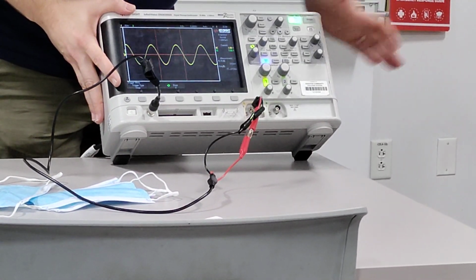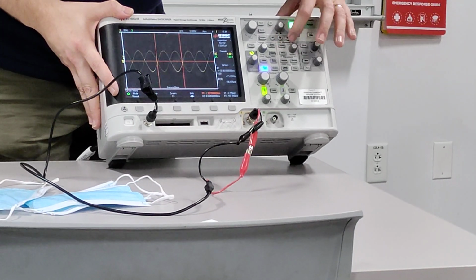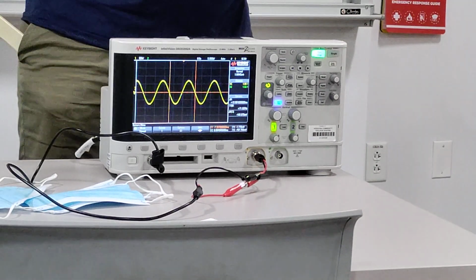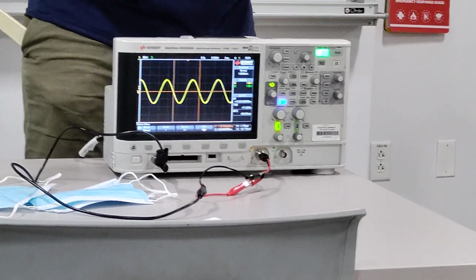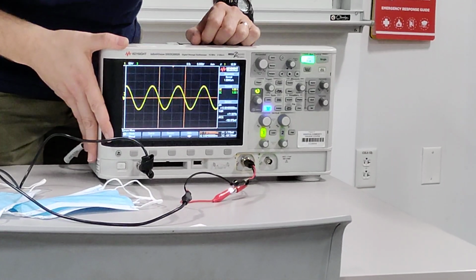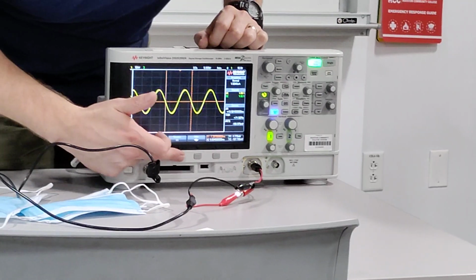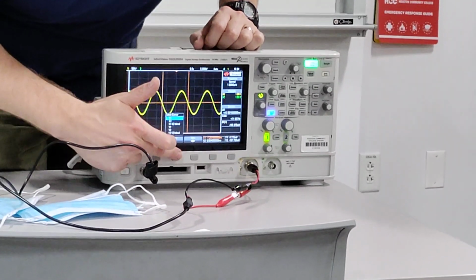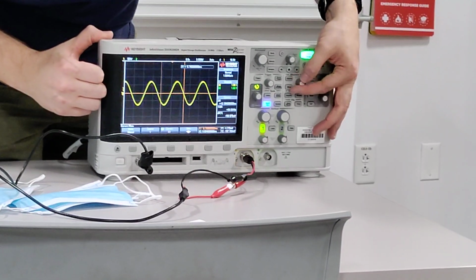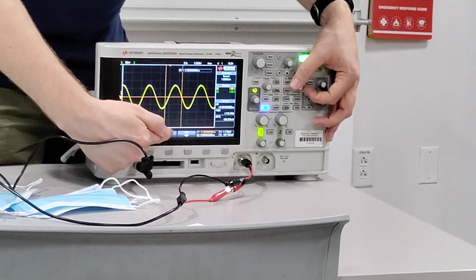Okay. There's a couple other useful things. There's a button here called cursors, and you have 2 x cursors, 2 y cursors. And you can set them where you want them, and it'll give you information on the right-hand side about what you have done. So, we're on source 1. I've got cursor x1.